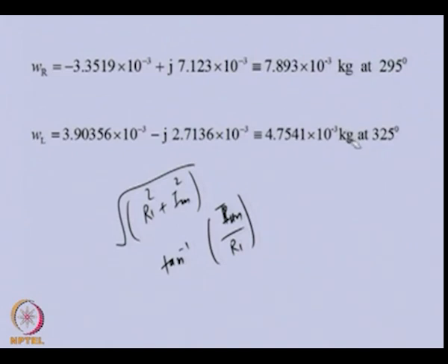But in this we require the phase information, which is very important, and because of that we could reduce the number of measurements drastically as compared to the cradle balancing machine procedure. So in today's lecture we first saw the graphical method for the cradle balancing machine. In that we saw how we can reduce the number of measurements as compared to the hit and trial method, and systematically we need to measure only 8 total measurements to obtain the balance correction masses in both planes of the rotor.